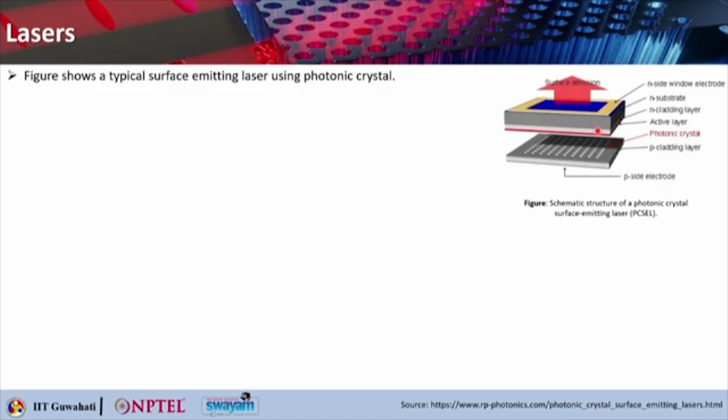The active region is separated from the photonic crystal structure by a thin electron blocking layer for keeping the electrical carriers confined in the active region. The active layer close to the photonic crystal layer excites band edge modes in the latter. It is pumped using N-type and P-type cladding layers and metallic electrodes at the bottom and the top.